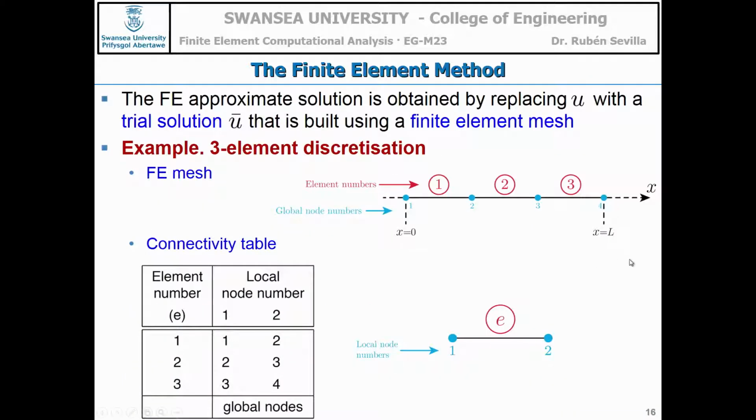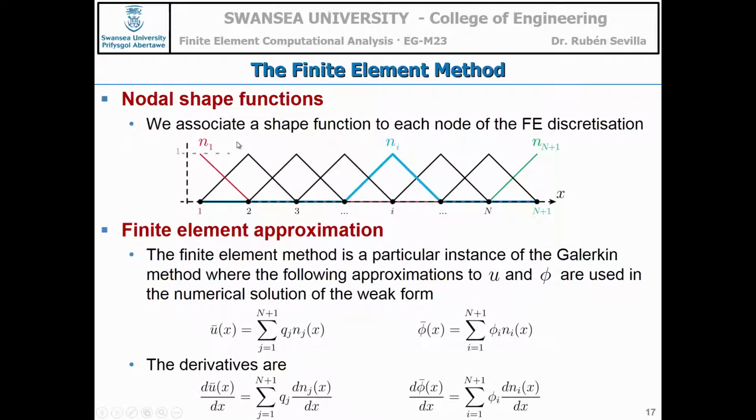And then we say, look, we are going to try to find a particular approximation of the solution. The simplest thing we could do is subdivide the bar in elements. In each element, use a linear approximation. That means that you are combining these piecewise linear functions, these hats. And the only thing I'm saying is that we are going to look for an approximation of this form, where the ends are these hat functions in there, and now the objective is to find the coefficients Q, numbers. So instead of finding a displacement field, a displacement function, we are after numbers, and everything looks a bit easier